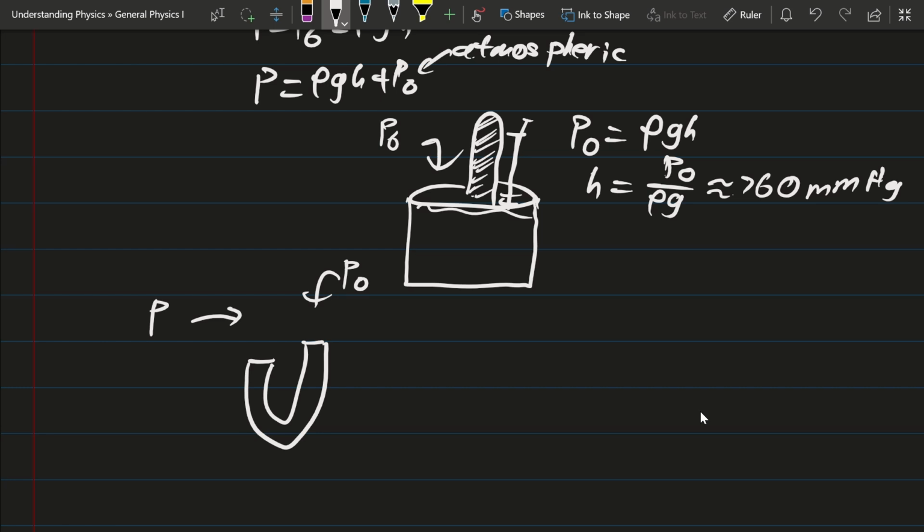And you could figure out what's the pressure in here based on the difference in the height. So if you actually think of this to be P0 plus rho g delta H, this must be equal to the P. That's basically the idea. You could figure out what's the change in the pressure thanks to the hydrostatic equilibrium. So that's another idea that you could use hydrostatic pressure.